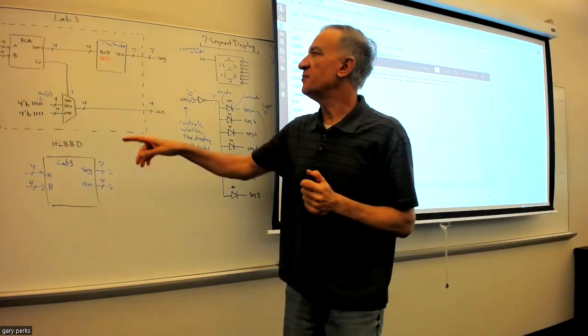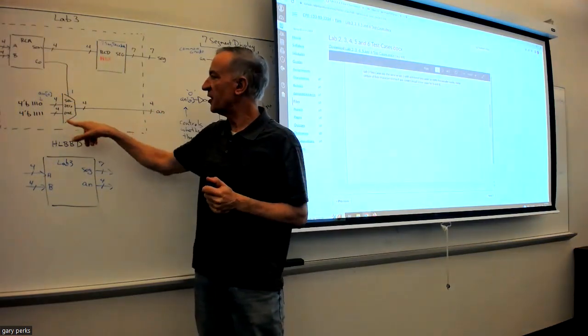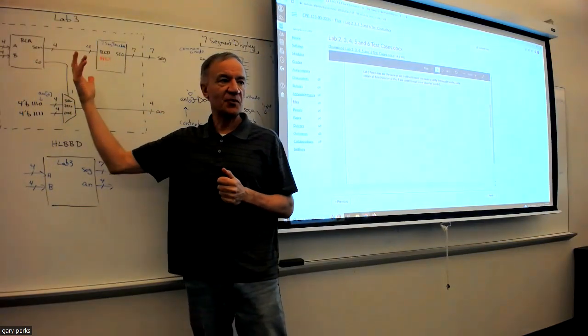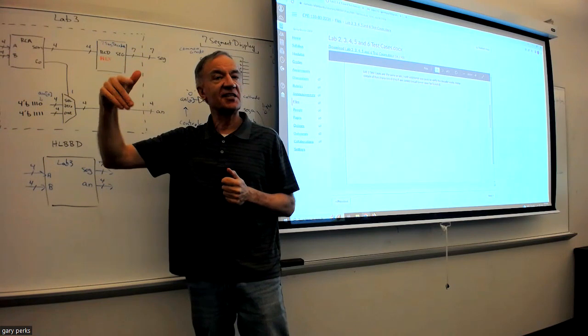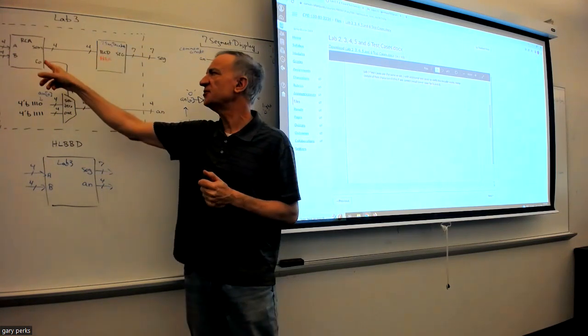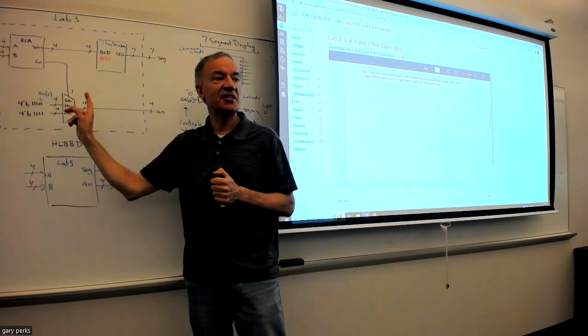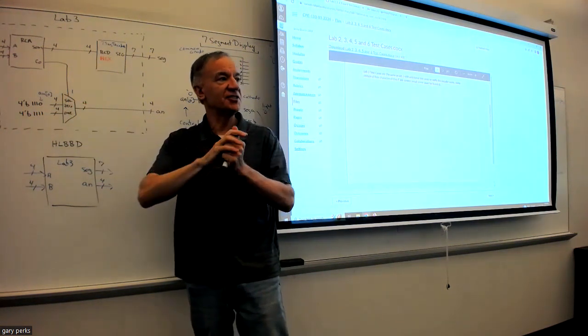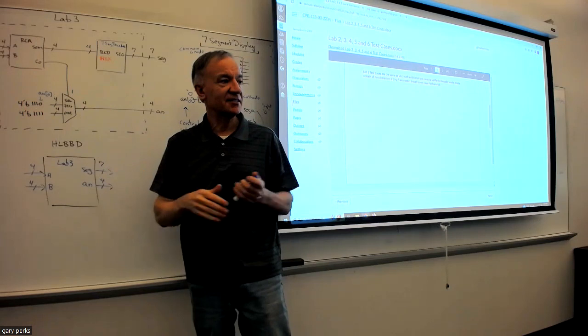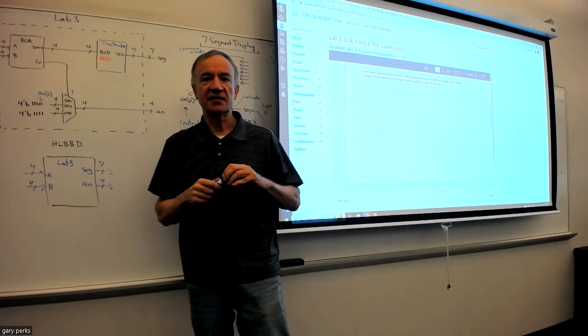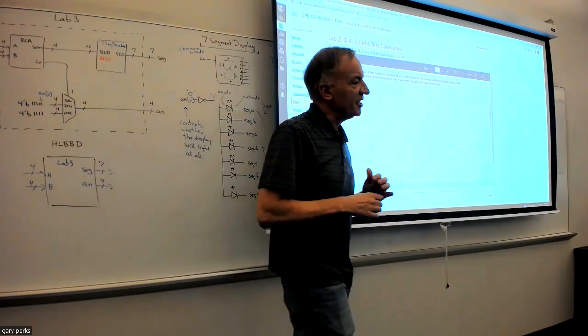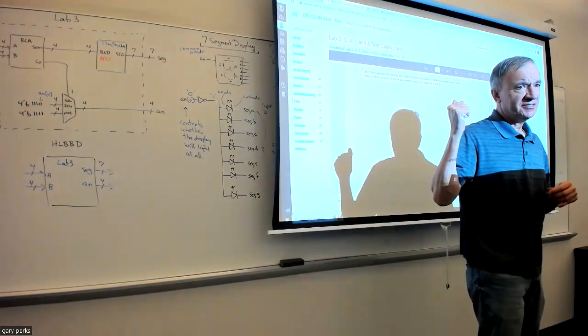Also, you want to make sure that this part of the MUX is working, right? That when you get a result more than 16, at least one of the test cases when you're testing out the RCA will give you a result greater than 15. So you should see the display blank. Okay. All right. So any questions on the test cases?